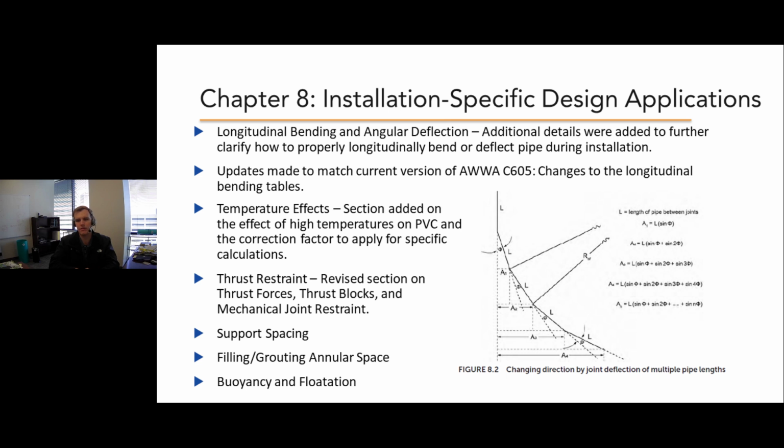and that's been removed, not due to any real issue with the pipe, but because stipulations were added for the amount of force required to actually perform that bending from an installation point of view. It was determined that you might need mechanical force to bend pipe that is greater than 8-inch at DR18, DR14 thicknesses, and generally it's recommended that you use manual force only when you're bending that pipe. So again, it's not any structural issue or any issue with the pipe material itself that caused that change. It's more a consideration of ease of installation; practicality drove that change.